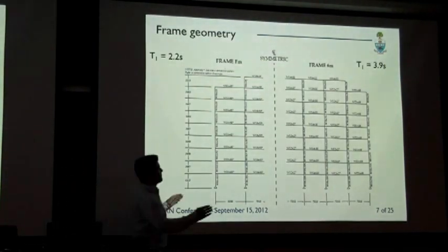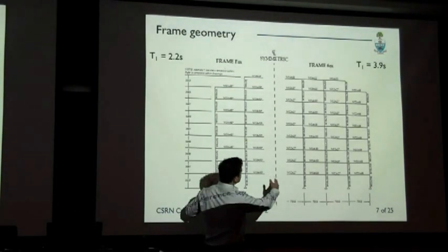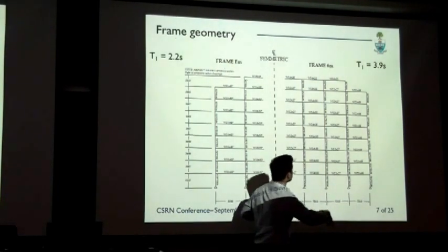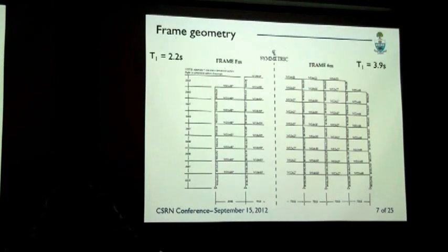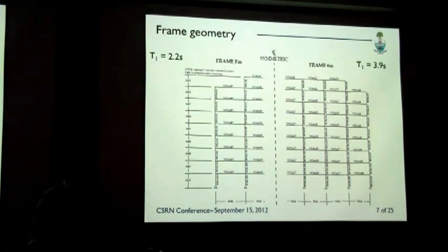This is half of the 3-bay frame, and this is half of the 7-bay frame, to give you an idea of what they look like. We did a spectral analysis for both Montreal and Vancouver, and we wanted to get an idea of what we're looking at. One of the things we did is we used the displaced shape from the spectral analysis to calculate the U2 factor to determine how important these P delta effects are.